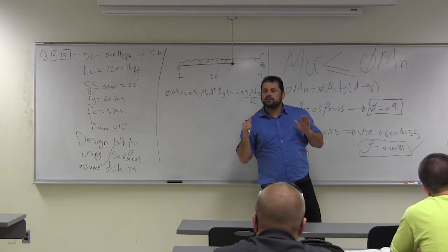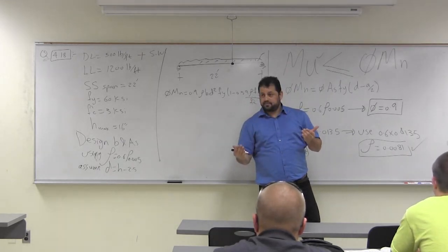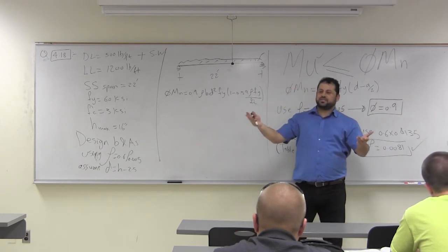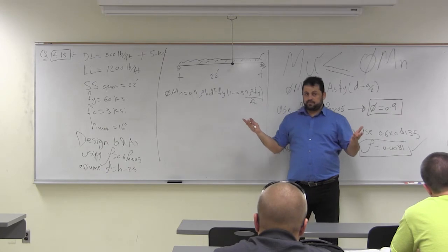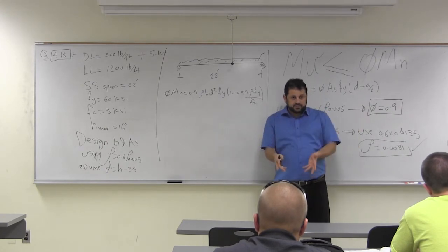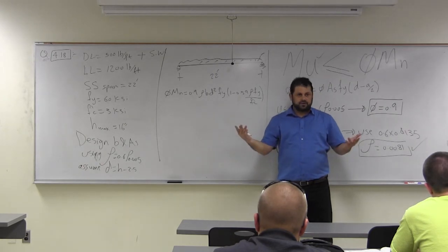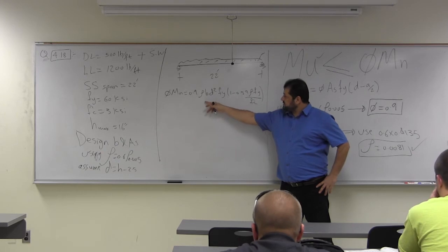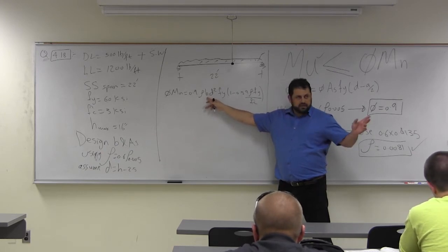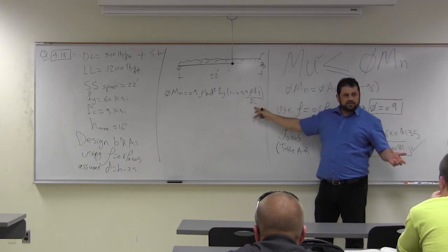Why? Maximize h as much as we can. Why? Higher moment of inertia. So it's deflection. Smaller steel. More concrete, smaller steel. Steel is more expensive than concrete. Good? So d is known. He wants us to calculate b. Okay, unknown. Rho, just calculate, fy, f prime c.